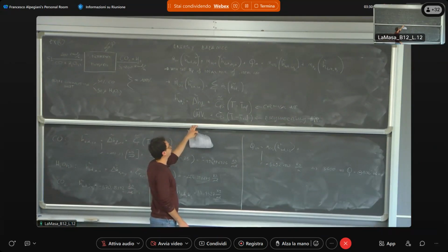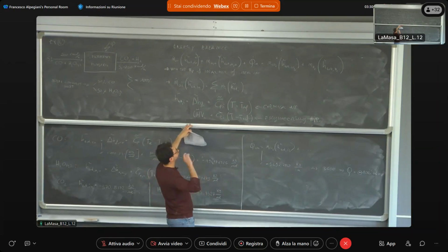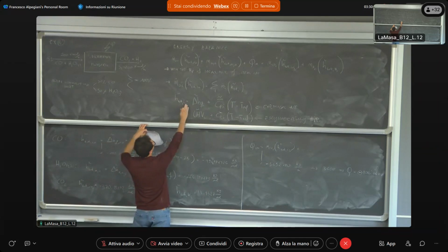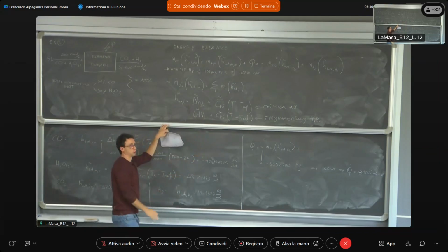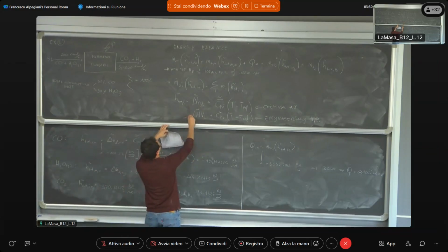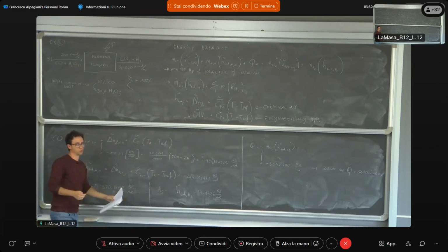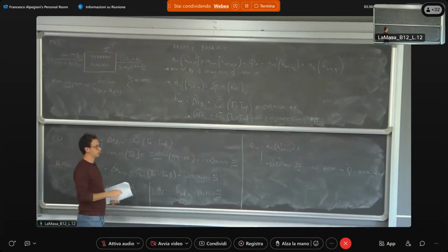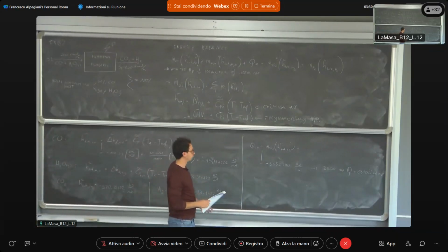Essentially, if you use the same approach, so you write the energy balance, but instead of evaluating the total enthalpy of the species with the enthalpy of formation, you use the LHV, the result that comes out is more or less the same. It's difficult to have exactly the same value because finding the lower heating value with the same approximation as the enthalpy of formation is different.